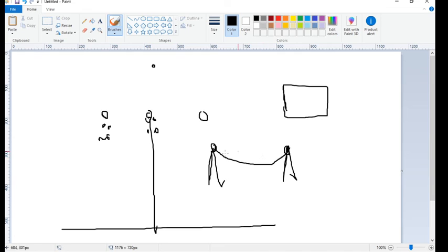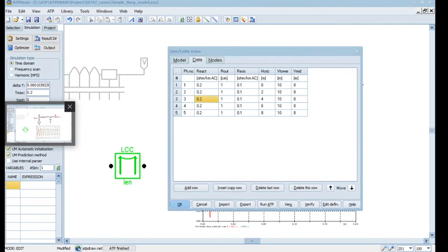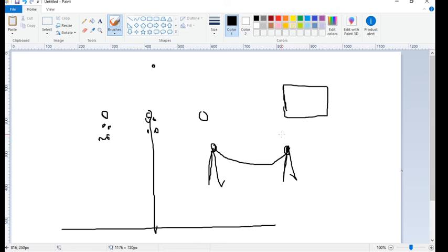So if you come back here in the settings, it specifies the tower height of that conductor. Let's say the first phase is a ground conductor, the second conductor is the R phase first conductor, then Y phase first conductor, and so on and so forth. So you need to specify the tower height, or at what height it is located. And V mid is also specified, actually between 2 towers, the middle, where the sagging happens, like what is the distance of the length happening. You need to specify this for each conductor.